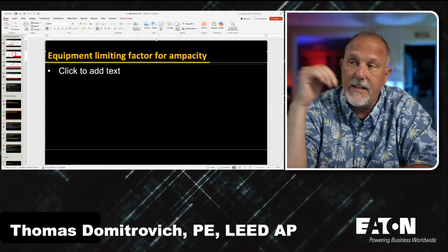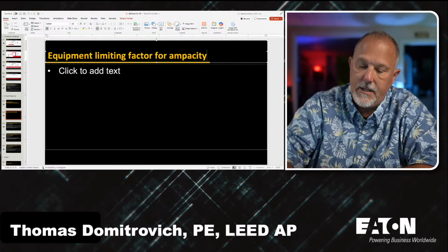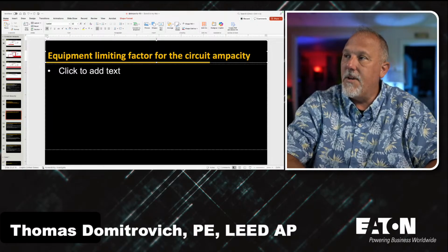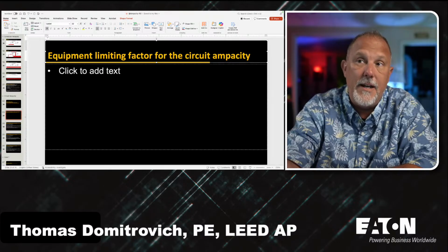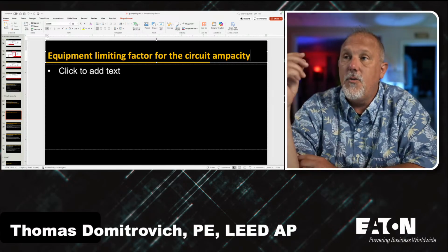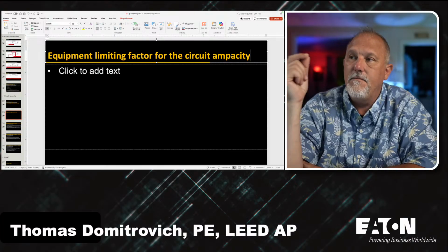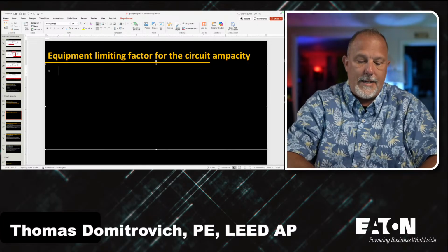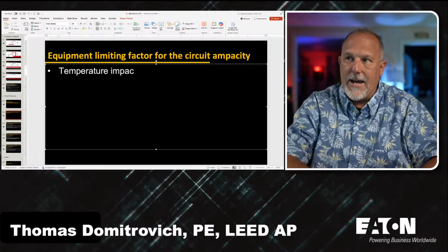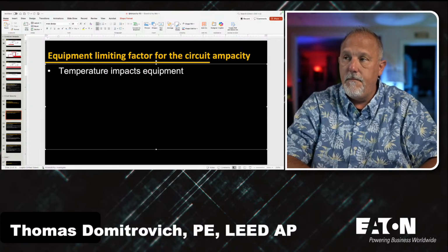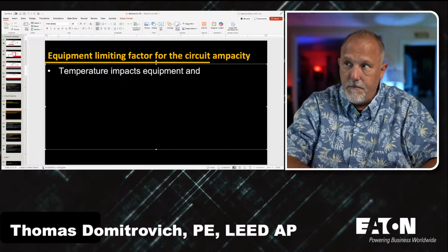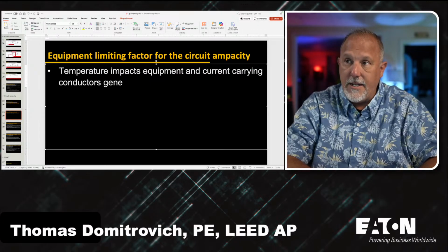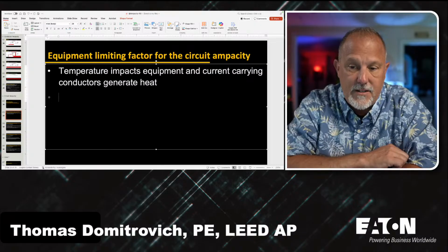I can't say for ampacity, so for the circuit ampacity, because when I use the term ampacity by itself, it's a defined term and it deals with a conductor. The equipment is an equipment limiting factor for the circuit ampacity. We know that temperature impacts equipment and current carrying conductors generate heat. We know that. That's a fact.